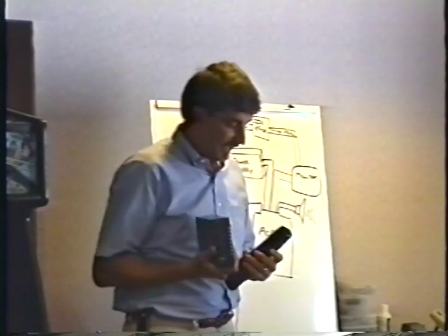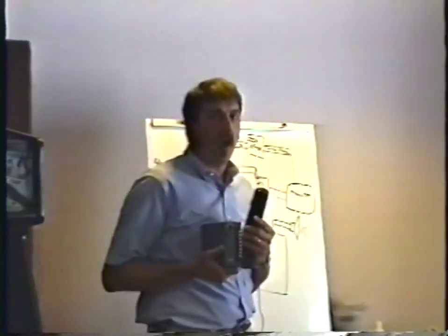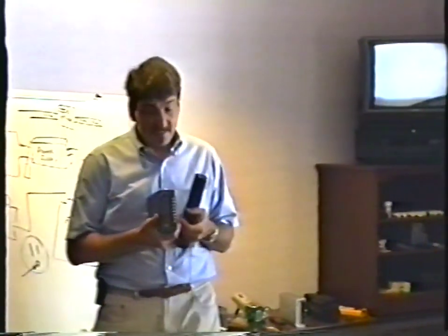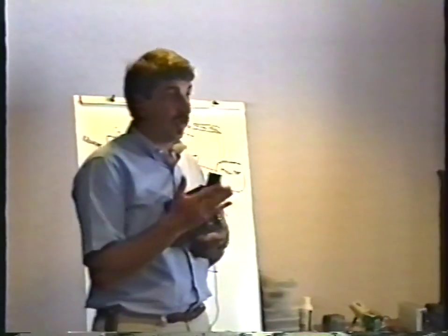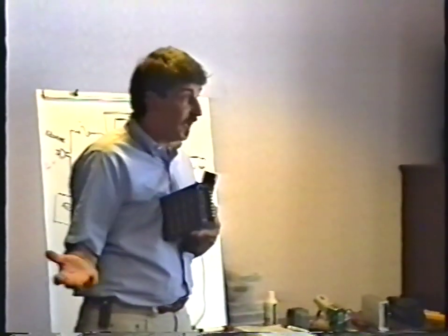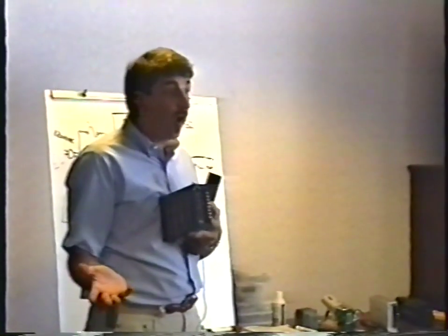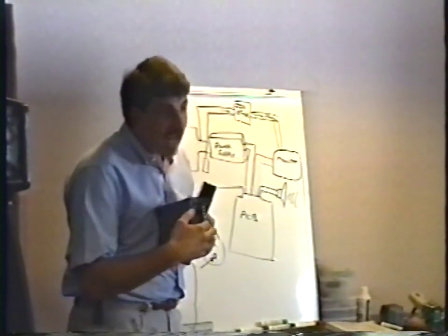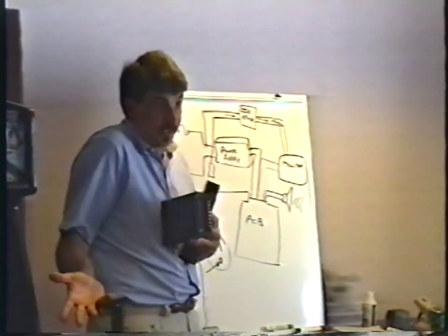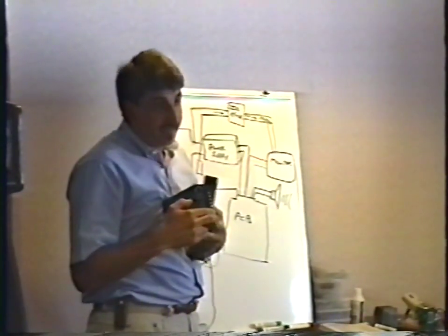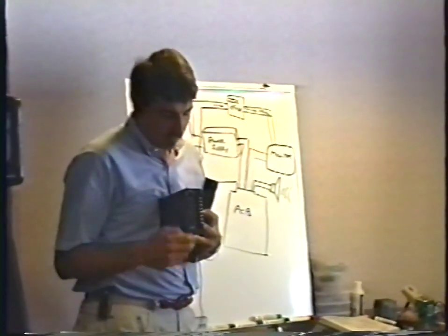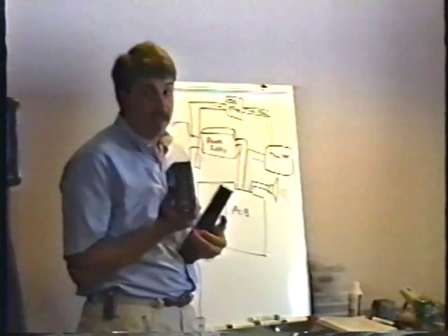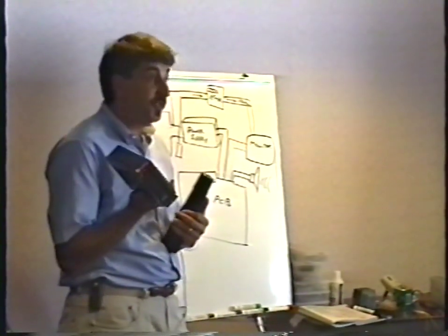Well, we have a saying in electronics, and the saying is garbage in, garbage out. What garbage in, garbage out means is that when you get a bad output from something, garbage out, check the input. If the input's garbage, obviously the output's going to be garbage too. What I'm saying is, okay, you don't have 5 volts coming out here, check the AC input. Make sure you got your AC in. But if you have your AC input, which you probably will, to be honest with you, and you don't have any DC out, then the power supply is bad, of course, and that's how you determine that the power supply itself is bad. That's pretty simple, huh?